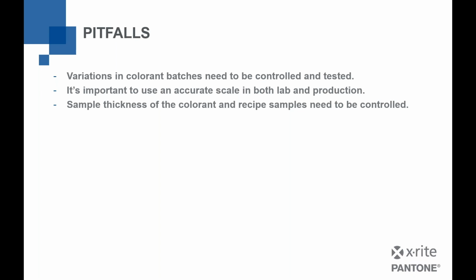When we formulate, we also can specify this is the film thickness we want to try to achieve a match. So you can have different film thicknesses. In the actual characterization of the pigments, we want to have the same film thickness. Now, you don't have to be perfect. You can actually measure the film thickness for every sample and input that.